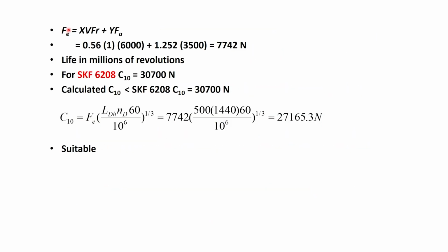The effective dynamic load as per our calculation is 7742 Newton. Now, this Fe will be substituted in this equation to get the required dynamic load of our bearing.